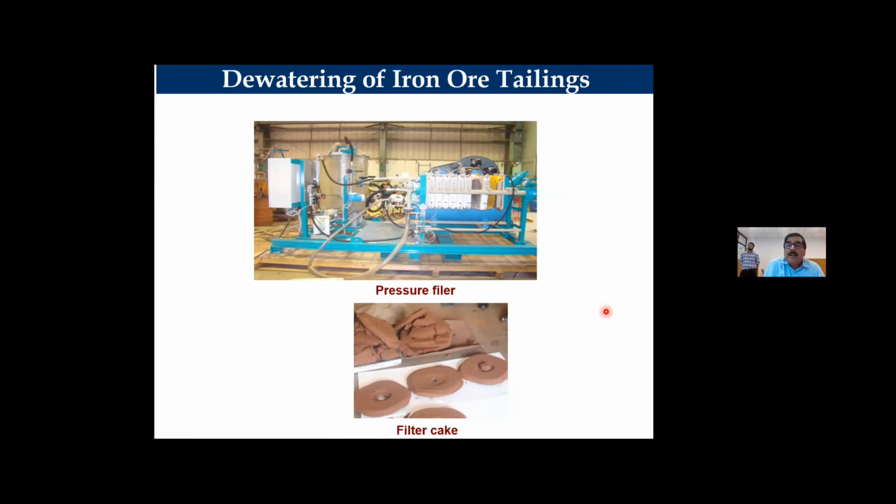And now the tailing issue all industry is facing, because the Ministry of Environment is not allowing tailings disposal. Now we are taking the step to make filtration. After filtration, you can stockpile. Because of the clay minerals, once you go below 45, the clay minerals are more. You have to use a conventional thickener, followed by a paste thickener. From the paste thickener, you go for the pressure filter.